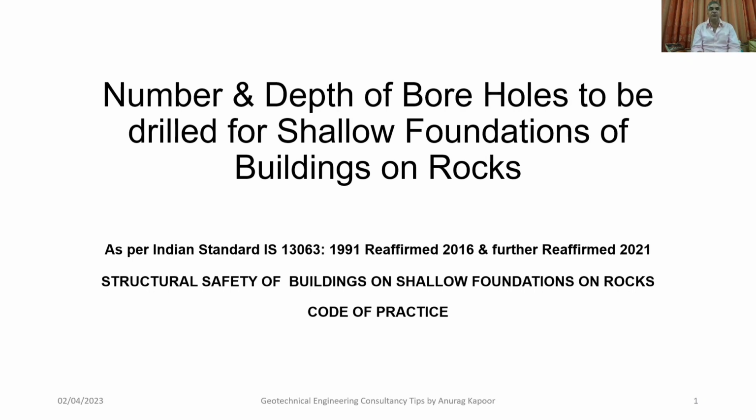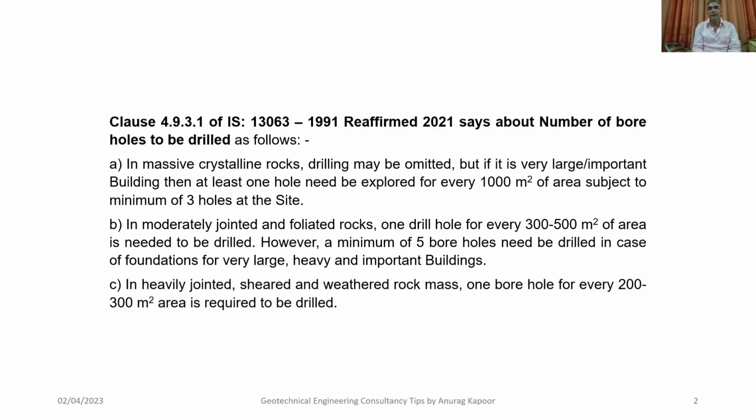Today I have decided to tell you about the specifications of how to decide the number and depth of boreholes to be drilled for shallow foundations of buildings on rocks as per Indian Standard IS 13063:1991, which was reaffirmed in 2016 and further reaffirmed in 2021. Structural safety of buildings on shallow foundations on rocks: code of practice. Now I would be referring you to the relevant clauses of this code only.